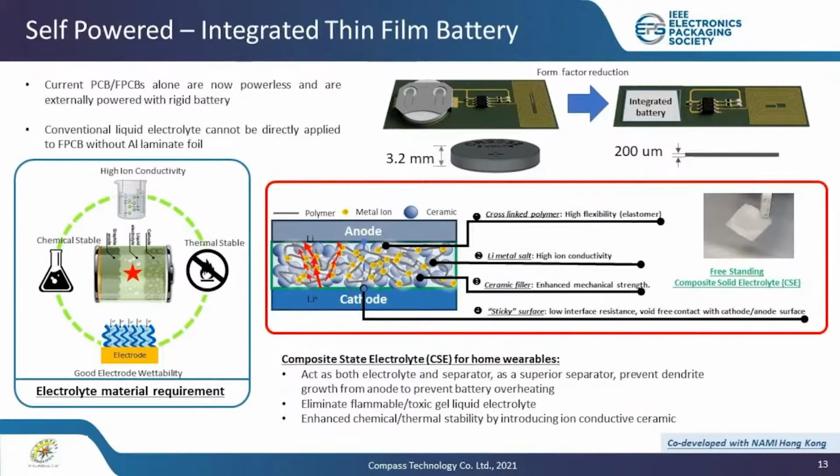Secondly, the lithium-ion salt needs to carry high ionic conductivities. Also, the ceramic filler is dispersed to improve the bendability of the integrated battery. Finally, the polymer surface is tuned to be sticky enough to ensure proper contact with the interface. This structure is able to improve the ionic mobility and stability during charging and discharging process. It also enables lower contact resistance.